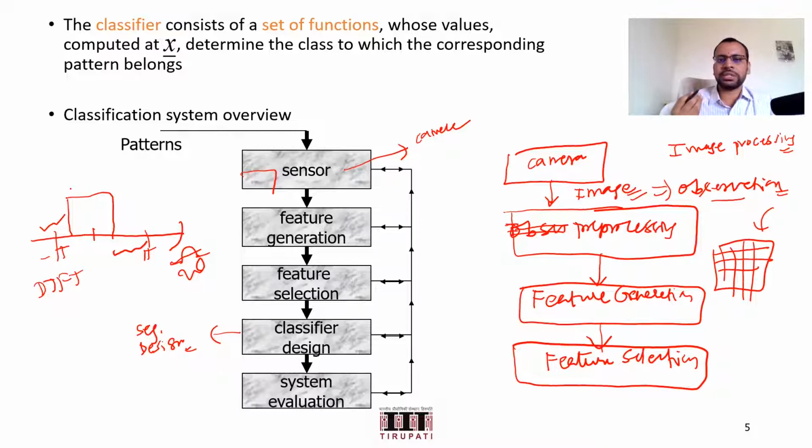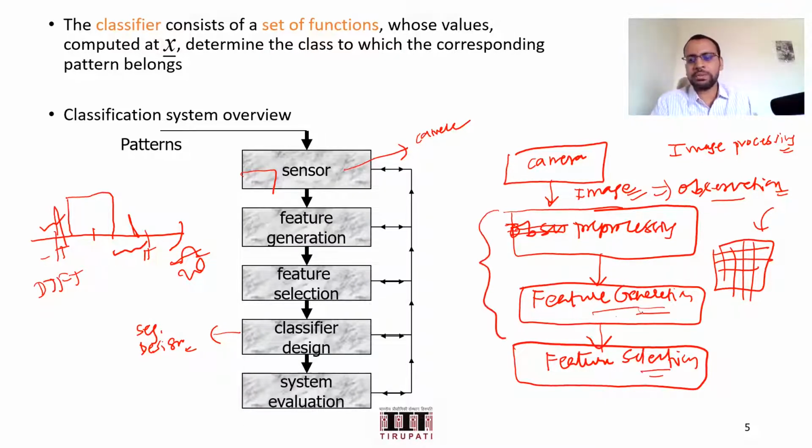And the third scenario is, even for this pre-processing, suppose I have noise lying here in my signal, in my spectrum. You take that signal into the Fourier domain, analyze it there, apply a filter there, and bring it back. That's what I mean by feature generation. Going to a Fourier domain and representing the signal is also one type of feature generation.